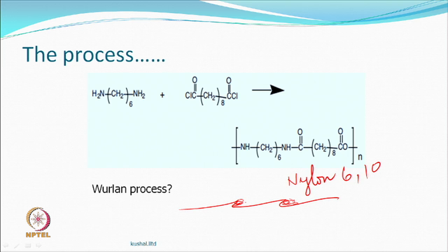Your aim is that if something goes here, then the friction in this direction and the friction in this direction would be more or less similar. So, that directional frictional effect which is responsible for the movement and the felting will be taken care of to some extent. Other polymers are also available. So, polymer coating is one of the ways in which you make shrink resistant wool. So, that is the possible solution.